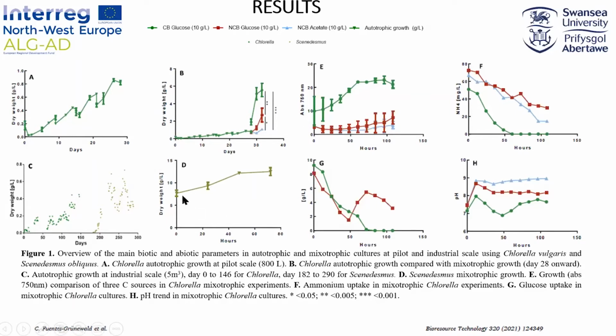I have to say the membrane technology is a quite good way to concentrate the algae, because you don't damage the cell, and that's quite important, because if you use any other kind of system, like for instance centrifuge, you will damage the cell. You won't be able to use that as inoculum for the mixotrophic reaction. In this case, we concentrated up to 7 grams per liter, and then we ran, and after 48 hours we reach over 12 grams per liter, which is pretty good as well.